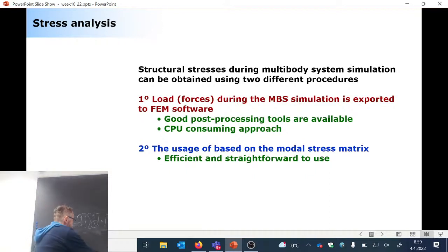Because in finite element, it's basically like this. Particularly if I look at the static cases, I have here the displacement that I'm solving, and these are all the forces that apply. And this allows me to describe these displacements. And from displacement I can get to strains, and from strains I can get the stresses. So that's how it goes in the finite element method.